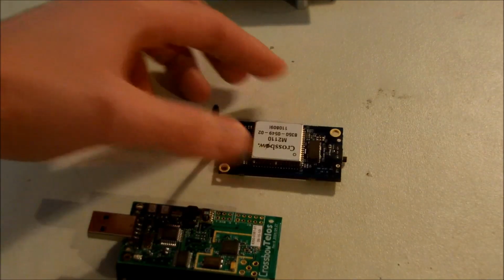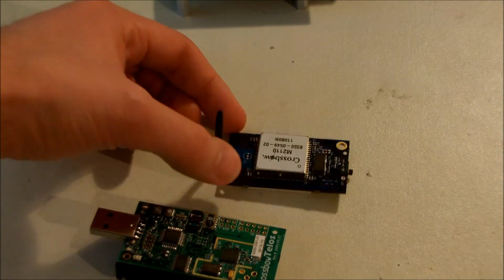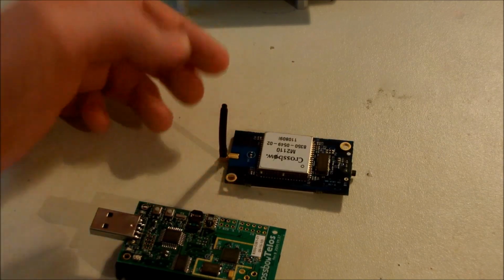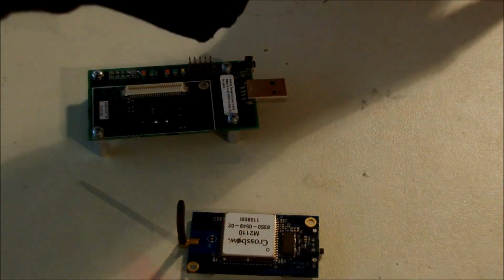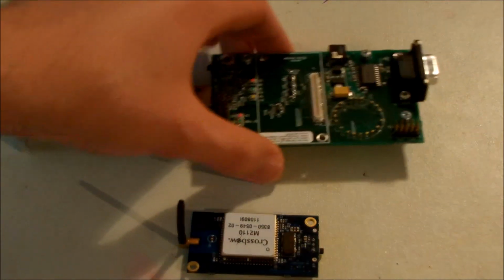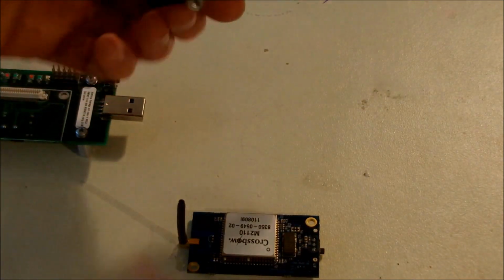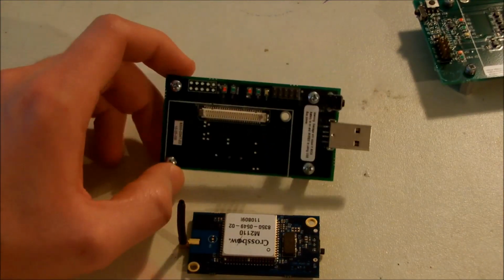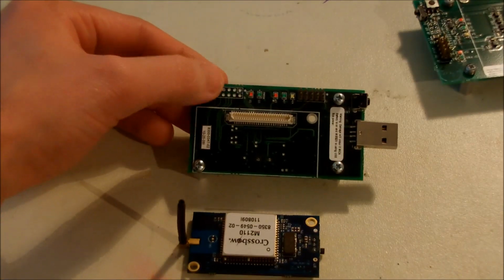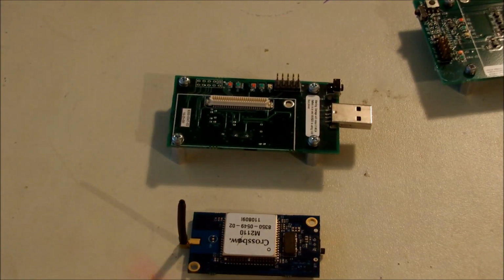For example, this Iris, while it has better communication range and so on, is not very flexible with expansions, and it comes down to which programming board you are using. This is the MIB510, the older model. As far as I can see, it doesn't have an expansion header, but the newer one, MIB520, also has an expansion header that allows you to add some analog stuff to it. So that's just something to be careful about. Yeah, so let's jump into the coding.